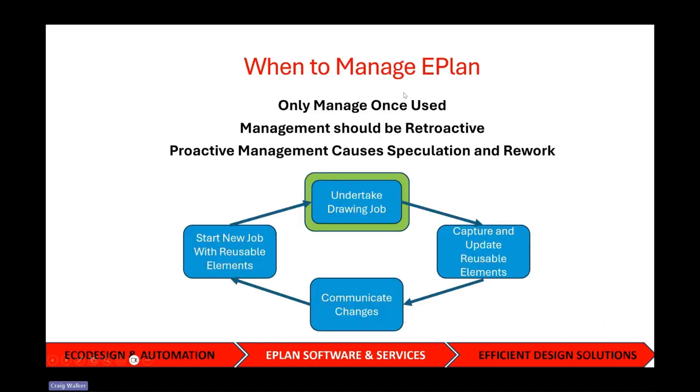Next, we have when to manage Eplan. The reason I put in the slide is we've seen people jump in and try and set up all their reusable elements right at the start, before they've used them. And what they often find is that the way they're actually using their elements when they come to use them is different to how they imagined they may be using them when they created them. So they've burned a lot of management time and then gone to use them and found it's just not going to work the way they wanted.